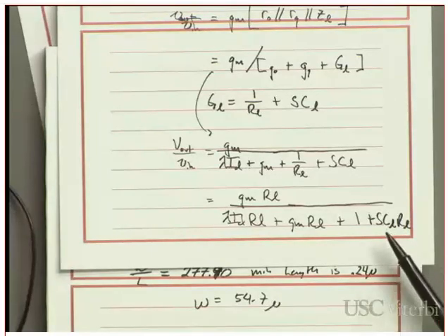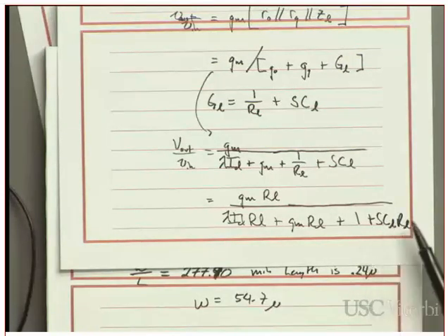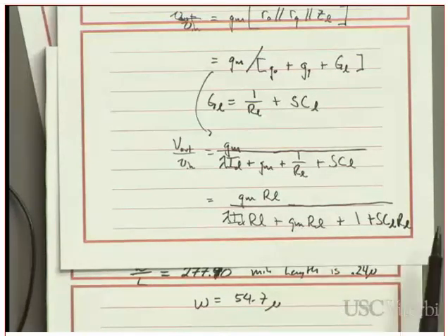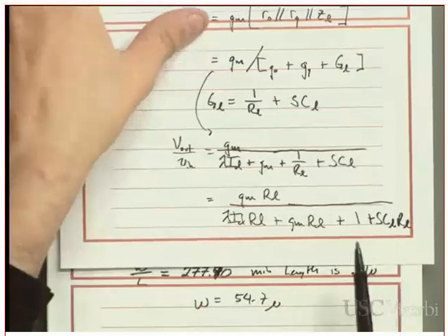And so if I know that my circuit actually does depend on the frequency times the load impedance, or load capacitance times load resistance, I can go back and try and fix that by designing a smaller load impedance, or trying to make RL even larger so that it's less of an issue.